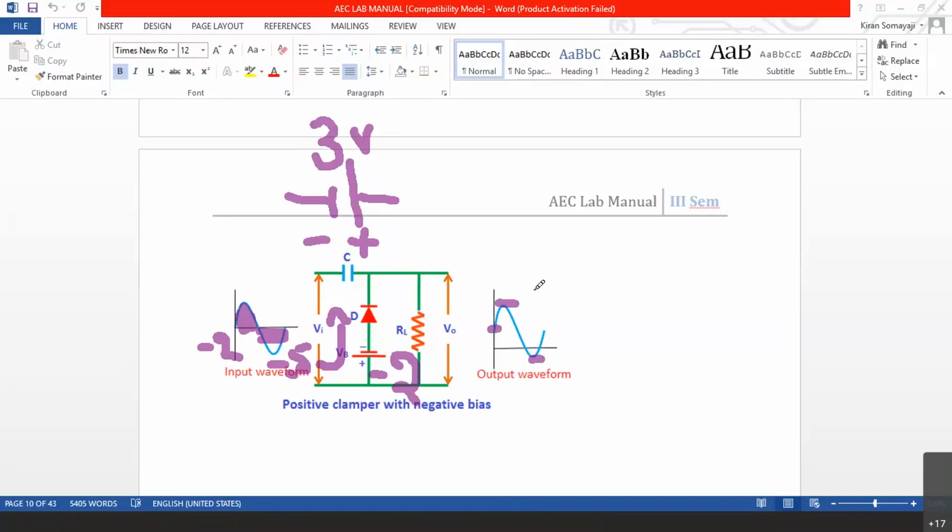Yeah. It was earlier 5 volts, now it is 8 volts. 5 plus 3, 8 volts. What about here now? Last below? -2. It is -2, because it was -5 plus 3 volts, which is -2. So the signal gets shifted upwards by 3 volts.